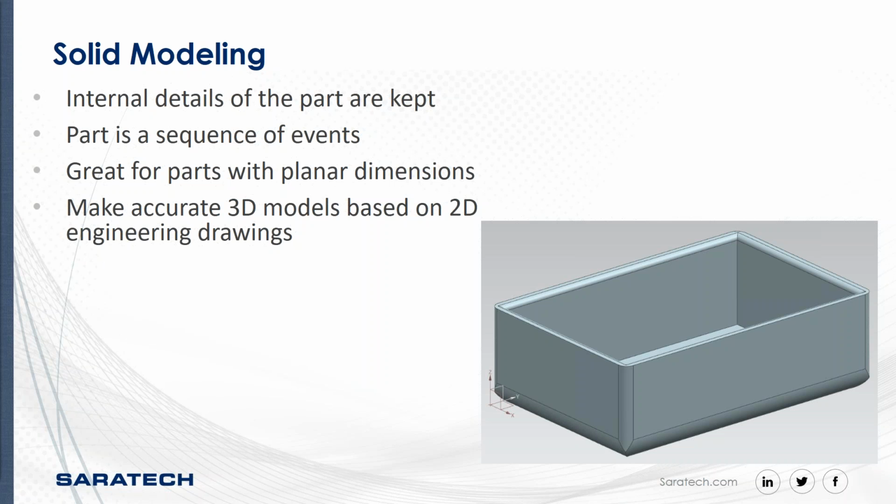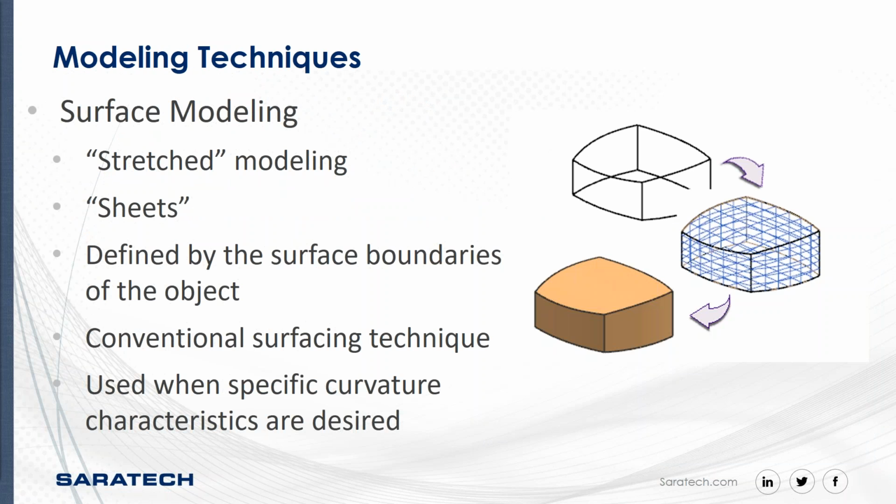Now, the other form of modeling is known as surface modeling, and this generally involves creating surfaces using splines. By drawing 3D curves in space with guidelines, we can create volumes in our CAD system by enclosing or following these curves. In other words, these surfaces are created and defined by the boundary of these curves. Now, why is surface modeling useful as compared to solid modeling?